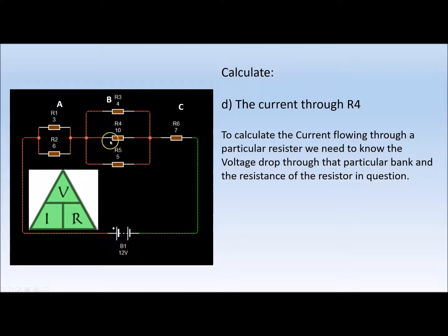So we are going to be looking at how much current is flowing through our 10 ohm resistor, R4. We had a total current of 1.109 amps here. As the current reaches a node, this point here, it's going to break up into 2 different directions, go through the 2 loads here, come back together, and then break up and go through the 3 different components here.